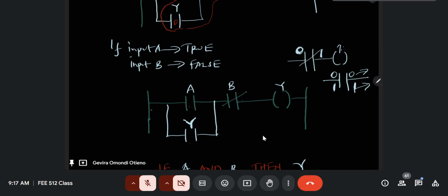The first scan cycle will complete everything. It will check A, B, Y as the inputs, then check the outputs. Because we don't have a second rung, the scan cycle will complete. Then it updates the outputs. It will come and check what is in memory location A. Memory location A is logic 1, so logic is passing through. What is in memory location B?